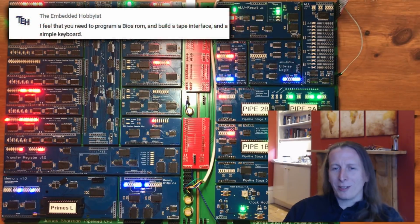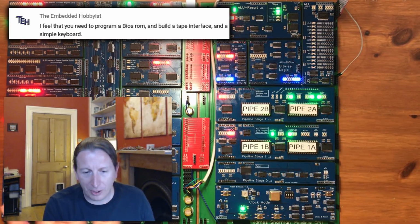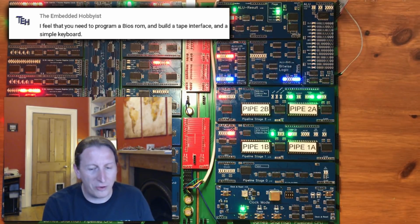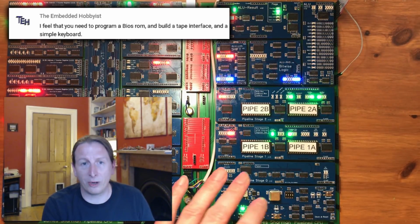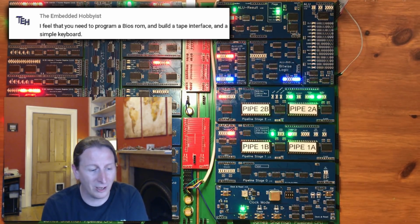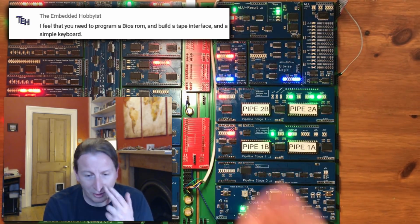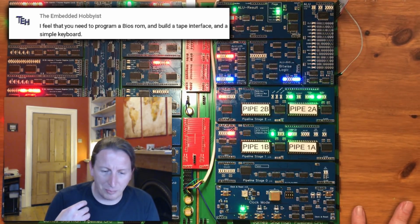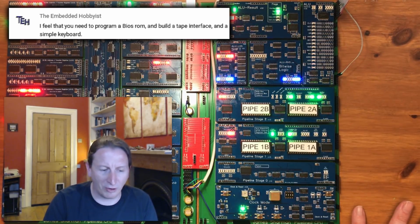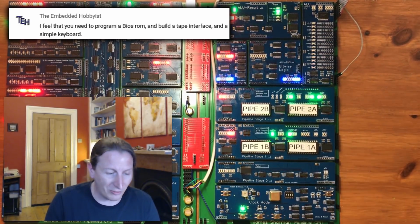The embedded hobbyist feels I should program a BIOS ROM and build a tape interface and a simple keyboard. I'm not going to build a keyboard because I've got the serial port. And if you compare the UART to, say, a PS2 type keyboard interface, it's actually a massive amount of commonality. So there's nothing really to learn or demonstrate doing a PS2 keyboard interface, and I can literally just plug in a PC with a serial program on and use my keyboard directly, or I could get a serial terminal and plug that in, and I've got a keyboard and I've got a convenient extra piece of output.